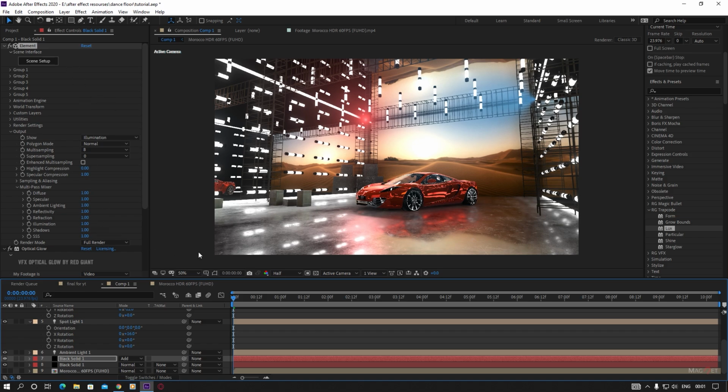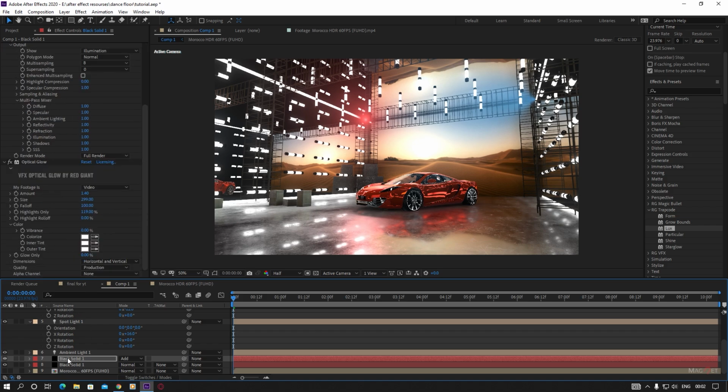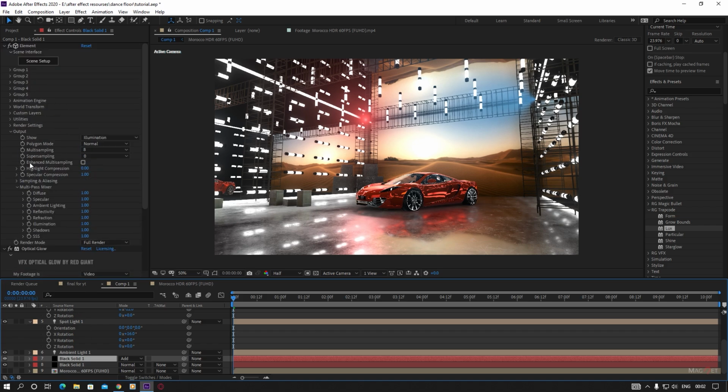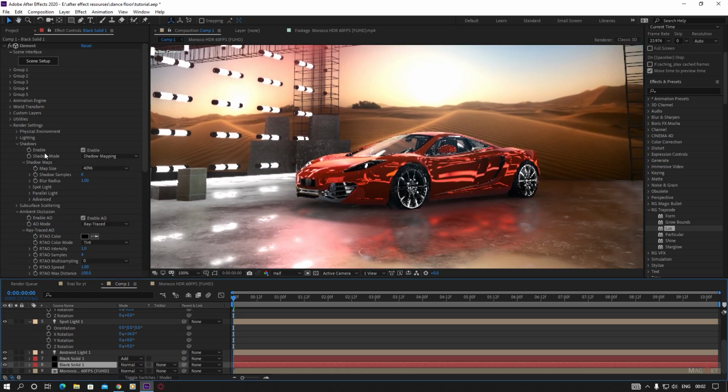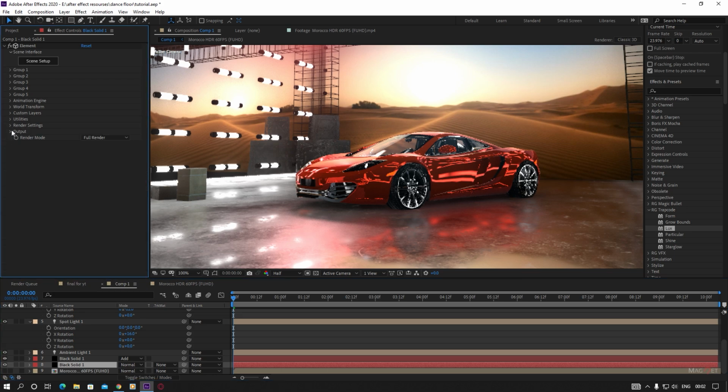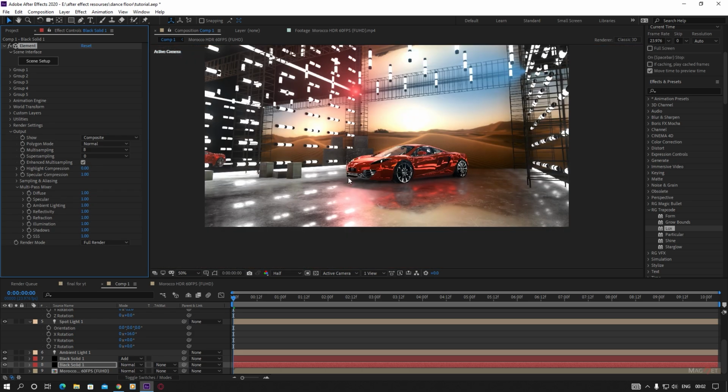So now we change some other settings here, that is make some super sampling here, that is the enhance multi sampling. We just turn this on. Okay, so instantly you can see some improvement here, and do the same for our main element layer. So go to its output and enable this enhance multi sampling. Okay, so now it looks nice.